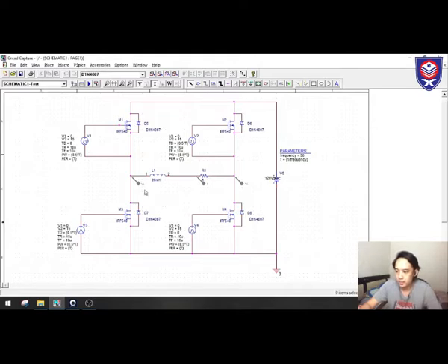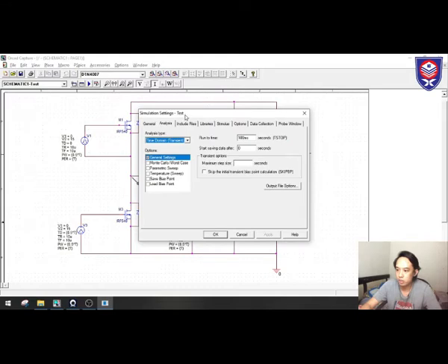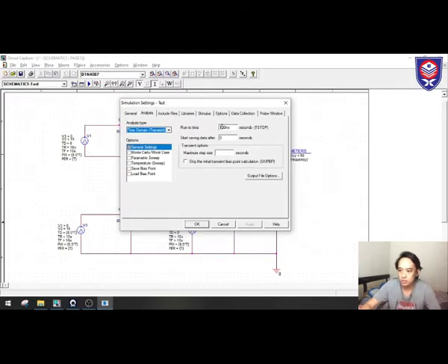So we can see I put 3 probes, positive and negative voltage and current probes, to read the waveform for the resistive load. So I try to run our setting for the simulation. In this setting the runtime is 100 milliseconds.